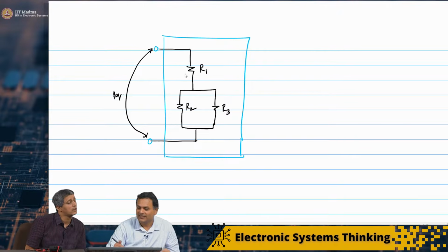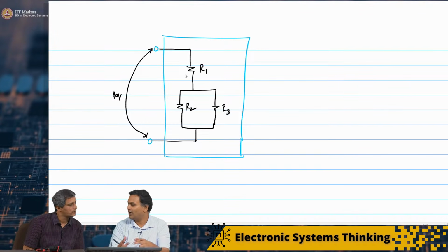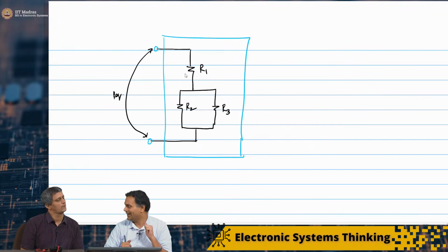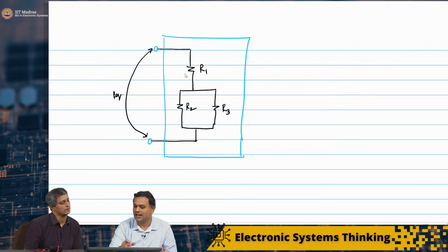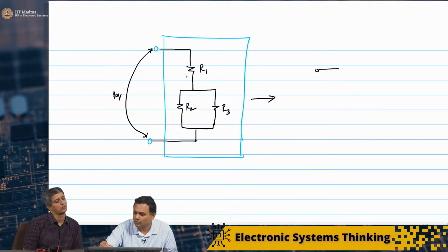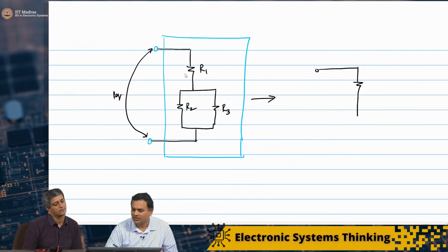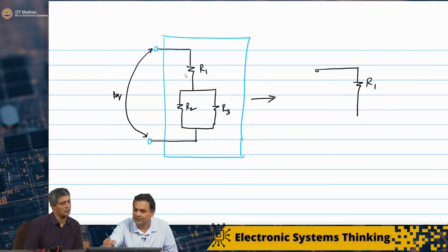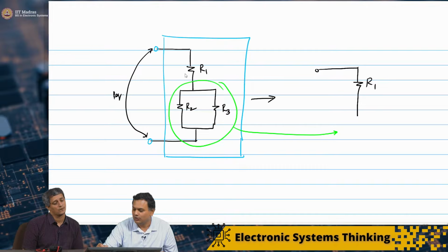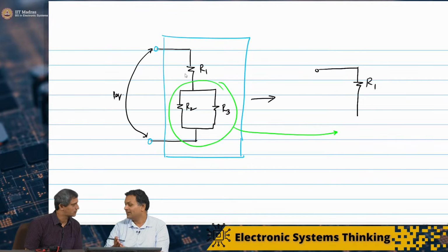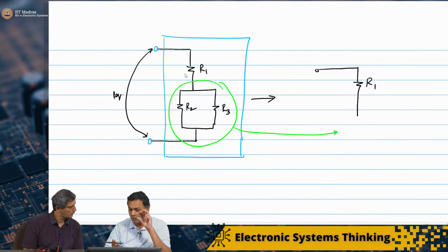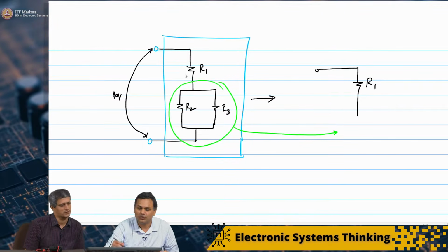So what we can do is start identifying how the simpler circuits that we saw apply here. Clearly the easiest thing to start off with is R2 in parallel with R3. So let us do that. We can simplify this network to, R1 remains the same. We are only going to take this portion, and we know that two resistors in parallel appear resistive again with an equivalent resistance, which is 1 over R2 plus 1 over R3. So we will write it like that.